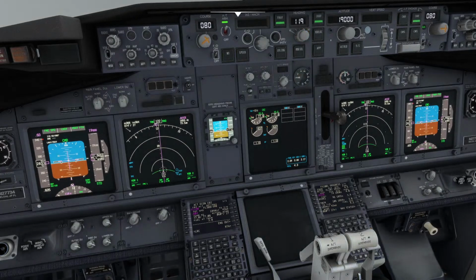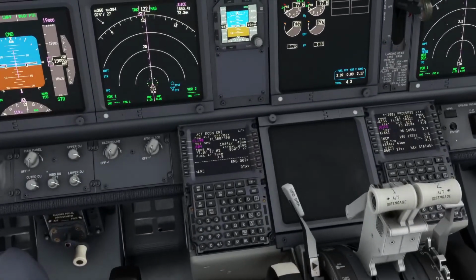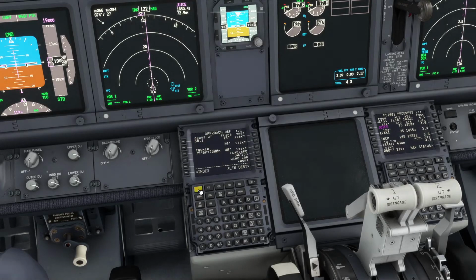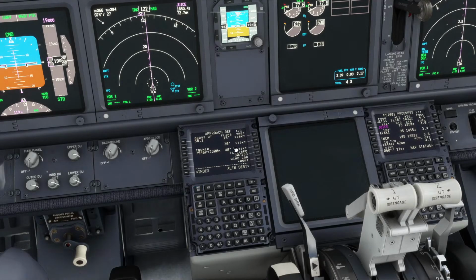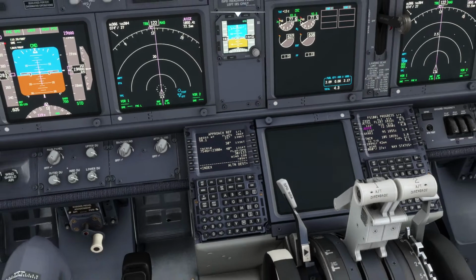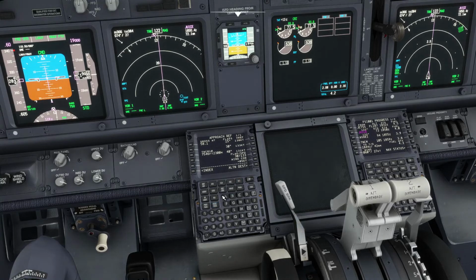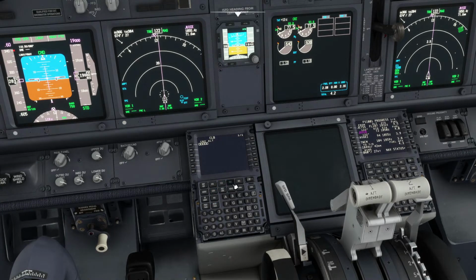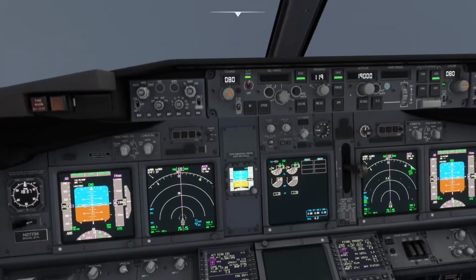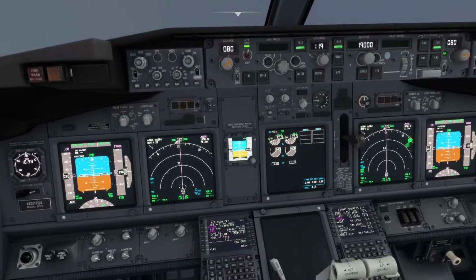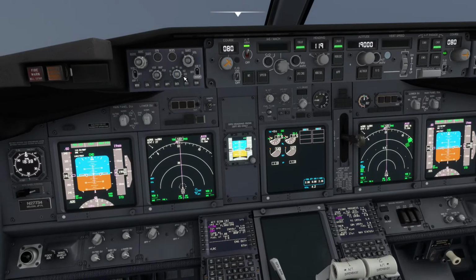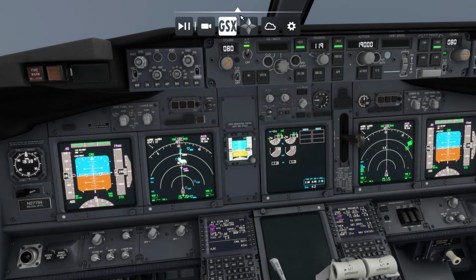Well, in this case, we will have all the flaps, and we have the system B. We are going to land with flaps 30. Yeah, not a problem to land with flaps 30, in case of go around flaps 15, because the flaps are working good. At this time that we are 40 miles to top of descent, it's a good idea to check for the weather at destination.